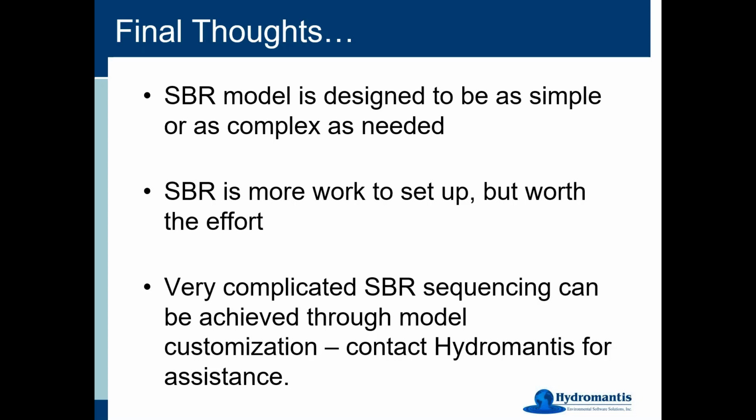And I did another one many years ago where the cycle was being driven by the oxygen uptake rate. And once that fell below a certain level, the sequencing knew that it was time to move on to the settling phase, and that kind of thing. So if there's something like that, just give us a shout and we can help you put in whatever it is you need it to do.